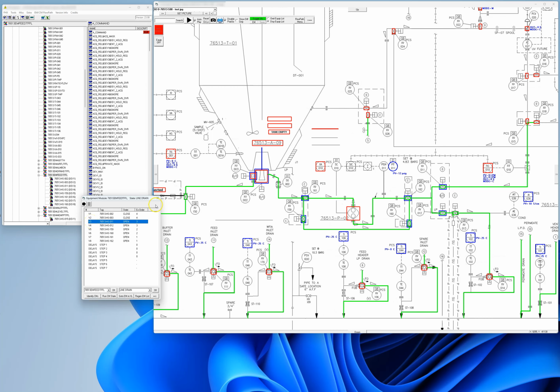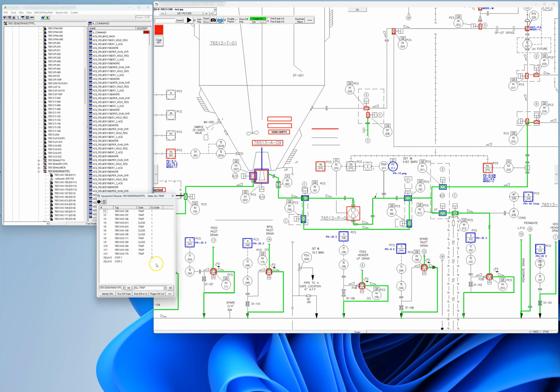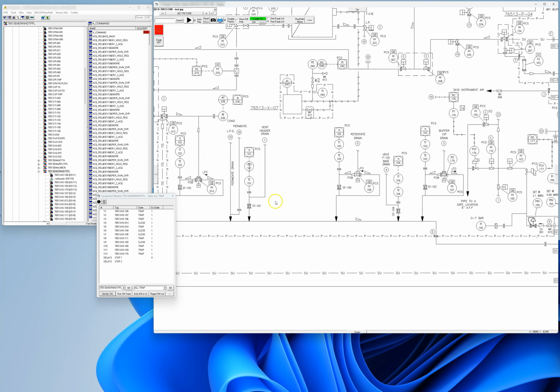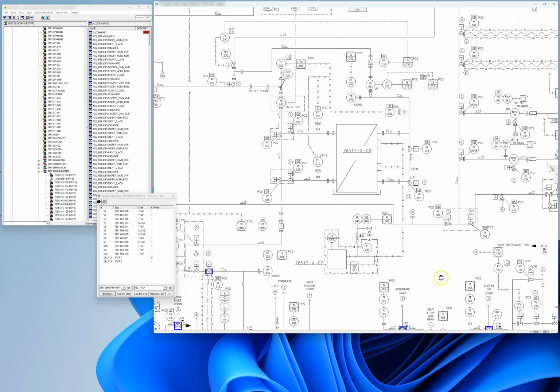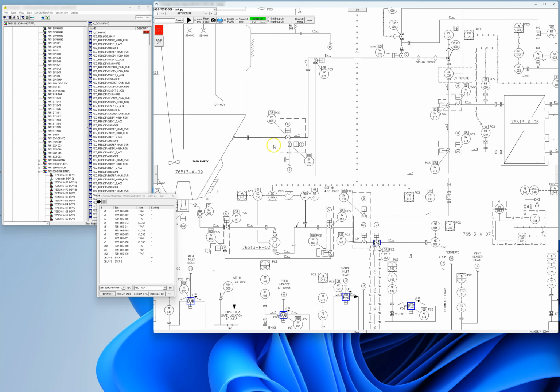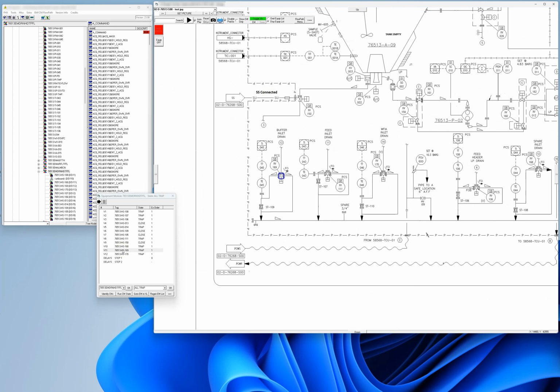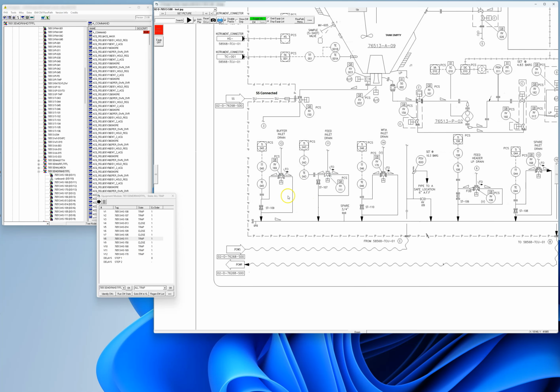If, for example, let's look at this EM, header drain, and these are a lot of valves, right? Open EM state table. This is how it looks like. If you say identify CMs, the entire P&ID is all over the place, right? Here and down here. What you can also do is you can select this, double click on it, and it'll bring you to that individual state in individual CM.